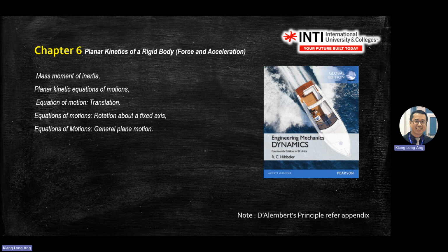Because in chapter 5 you have rotation, your body will go through circular motion. In circular motion, you have normal and tangent directions. So your acceleration will have AN and AT. Your AT will be alpha R. Tangent is the same as the velocity direction, so velocity direction you link with alpha R. AN is omega squared R. So these are all the equations that you need to memorize.